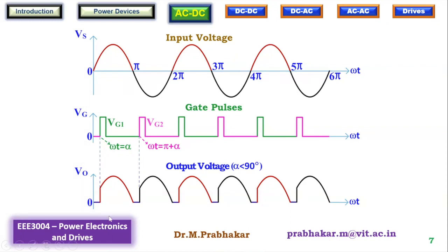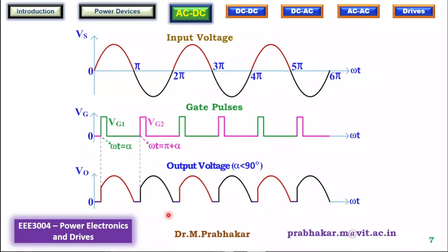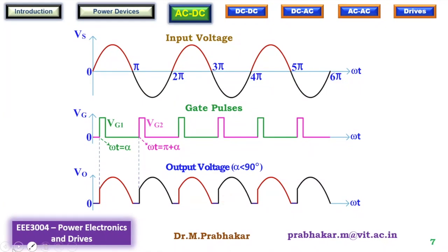Now, are you able to see any negative portion of the waveform in a semi-converter? Are you seeing any negative portion in the load voltage? No. Why is that negative portion not occurring, whereas in a half wave, it was there? Small negative portion was there. Load voltage was becoming negative when supply reversed. There was RL load. Here also we have RL load, but we are not seeing that negative portion. Why? Voltage is being short circuited.